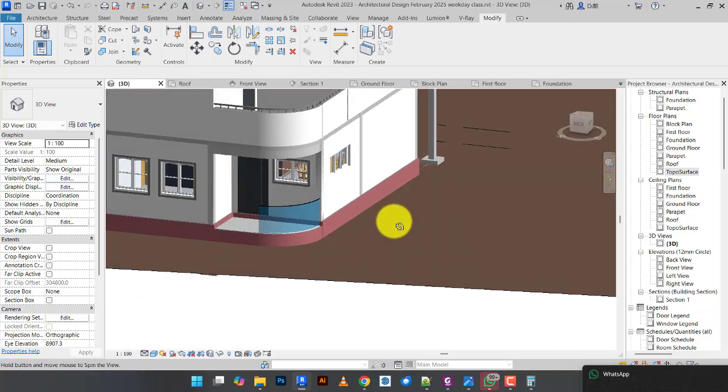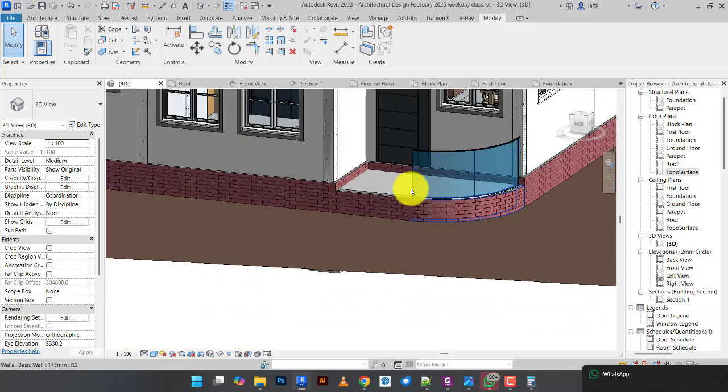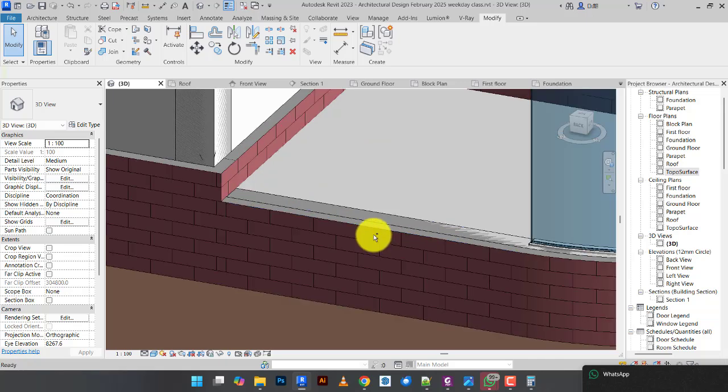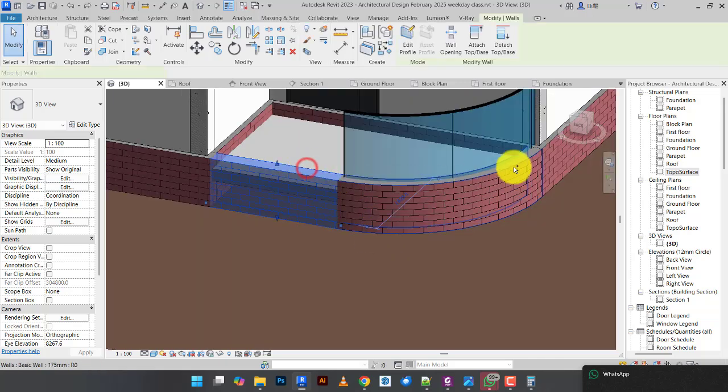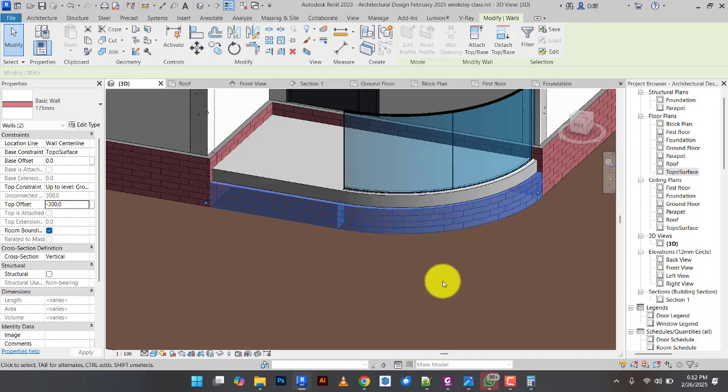I selected the slab here. See, the slab here is higher than the other one, so you can see that it's flashing here. So I'll undo. I'm unable to select the slab. So what I'll do is I'll use the top offset. Remember, top offset to reduce it. So I think here we'll do minus what? 300. 150 will come to the same thing as the slab. 124 under minus 300. So it falls under this way.